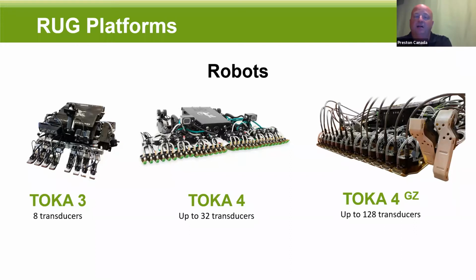So flanges and pipe supports are definite considerations when we're doing the inspection. What we typically do, and I'll use an overhead line for example, on an overhead line, a lot of times we'll work off a JLG man lift. We'll place the robot on a section and we'll run that whole section. Then we'll pick the robot off that section and move it to the next side of the flange or pipe